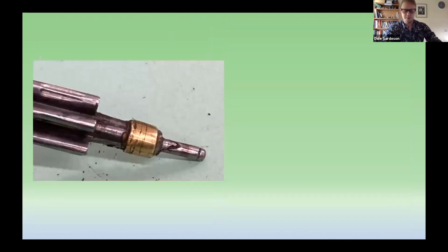Now this pivot is on the hoop or locking wheel. It's the front pivot, and you can see that there's a significant stress fracture in that pivot. The bearing surface itself is not significantly lost, but that stress fracture goes right the way through the diameter of the pivot and up into the arbor. And you can see someone has pressed and soldered a brass ring onto the arbor to reinforce it.